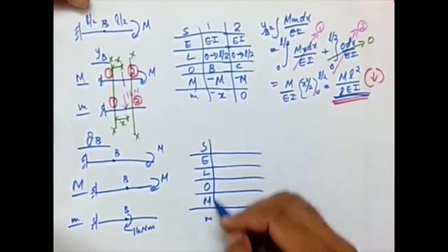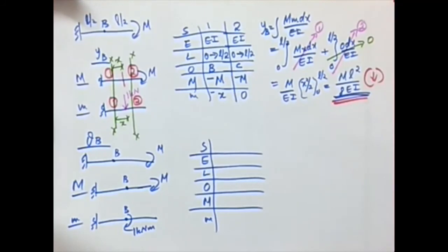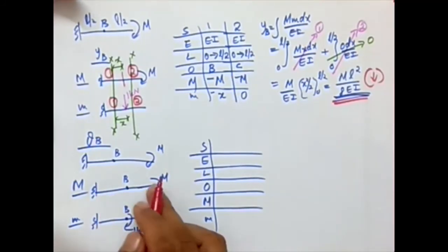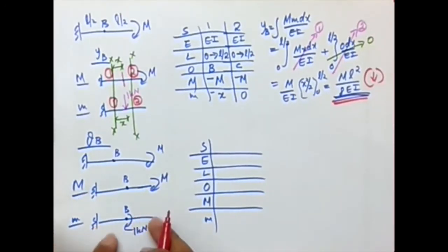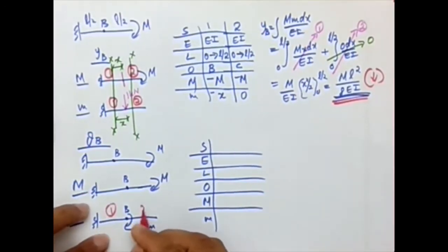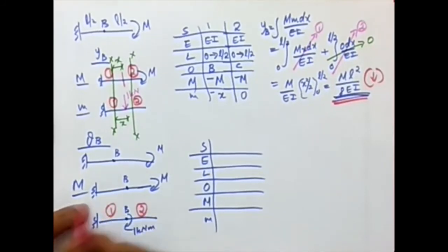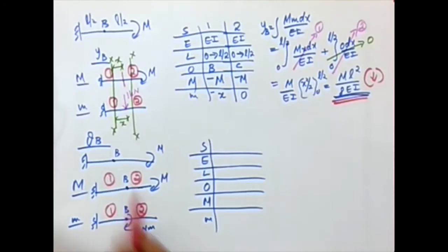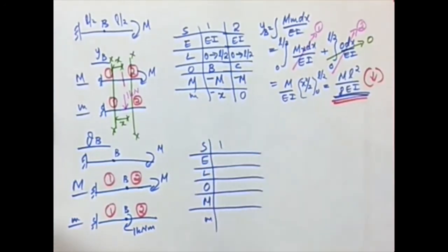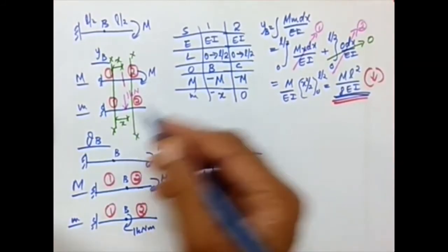So what about here? How many segments will be required? Point load, 1 segment, 2 segments. So here I require 2 segments, here only 1. So there is no way, we have to go for 2. Whichever is higher, we need to go with that. So here also we require 2 segments. So we are dealing with segment 1. Okay, EI is constant as given in the problem.